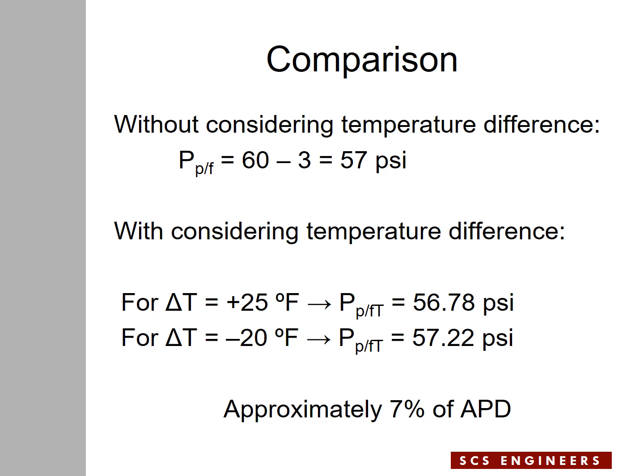Just to give you an example, I had a case 2 years ago in Miami at a site, which the result was a failing result based on the pass-fail pressure without considering temperature. But when we started looking into change of temperature, our results ended up being passing results.